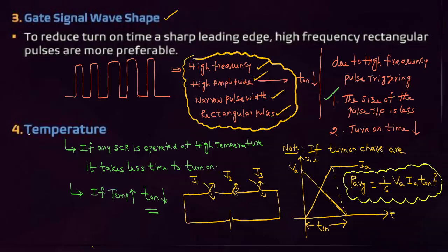And one more important observation: turn on time also depends on the temperature. The SCRs which operate at high temperature take less turn on time. That is, if the temperature increases, the turn on time also reduces.